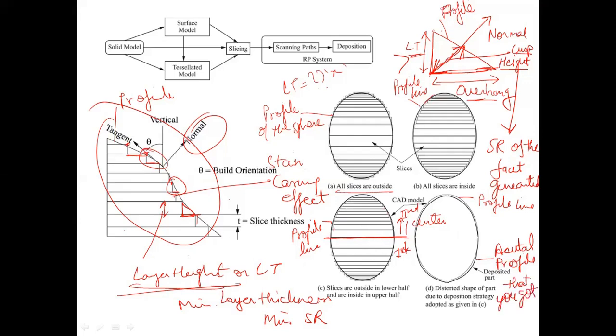So basically what you are doing is, you are trying to minimize the shrinkage of both the sides. I'm achieving the same amount of shrinkage by changing the philosophy of the part. So the outer part will be on the outer side of the profile line, whereas the inner part will be inside the profile line. So you will end up having a product which will not be, I won't say an exact replica, but it will be distinctly similar to the product that you actually wanted to use.